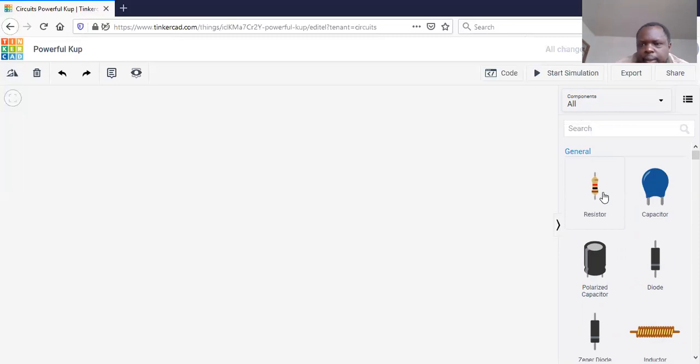One of them being the LED, where you need to connect a 220 ohm resistor to control the amount of current going in. A capacitor can be used to store energy and smooth circuits, but in most applications we don't use it. Maybe the advanced ones, but for basic applications I usually don't use capacitors.